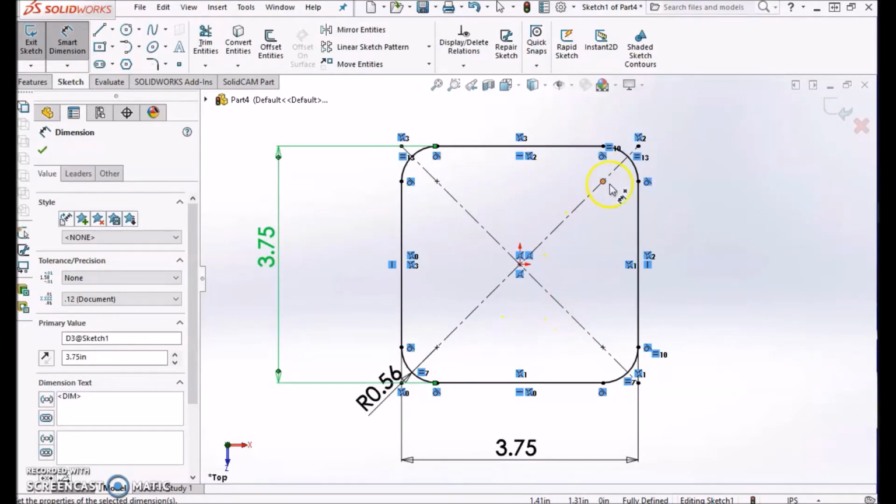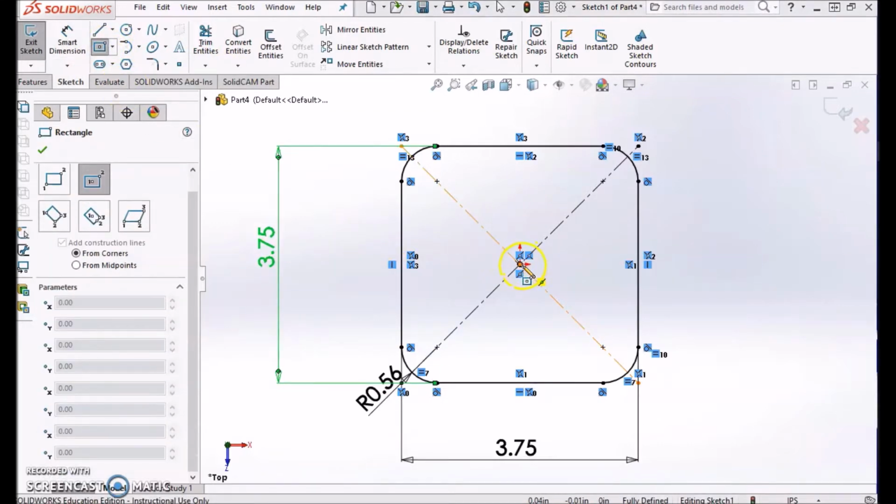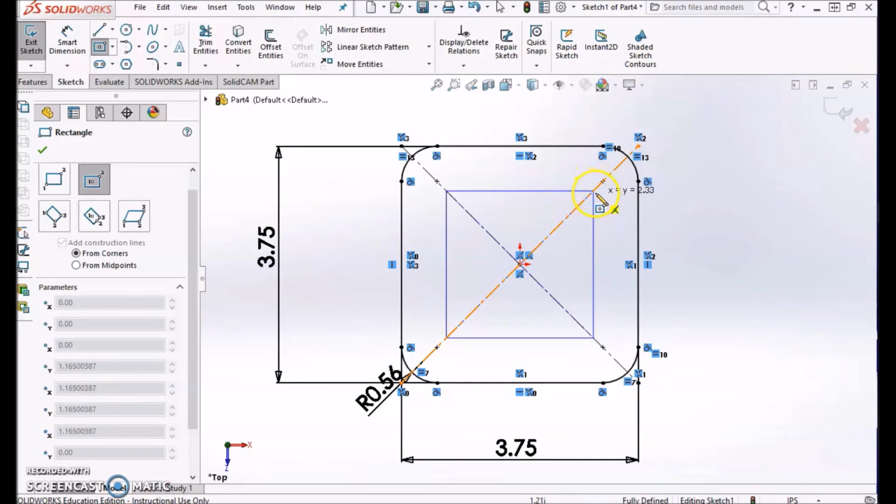And this is where I was talking about, here's the center point. Most people would put the circle right on it. But what we actually need to do is put the circle in a little bit. So I am once again going to get my center rectangle tool, and I'll be clicking on the origin and sliding out, and I'm not going to connect it to that center point.